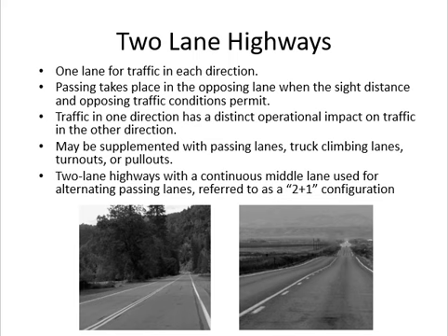Anything which is beside you affects you in terms of driving, whether it is moving or stationary. Okay, if it's a concrete barrier, still it affects you. If I remove the barrier, your driving behavior can change. Okay, if you remember in the analysis we were doing in the last chapter, you were taking lateral clearance and lane width. Why? Okay, because your width also affects you. Okay, what is happening on your side affects you.